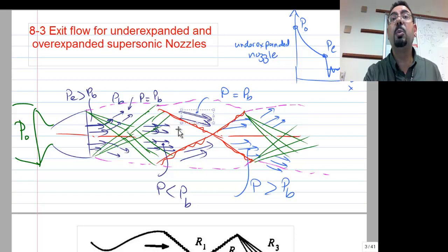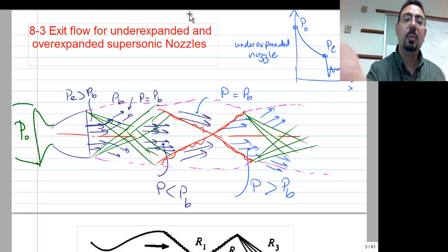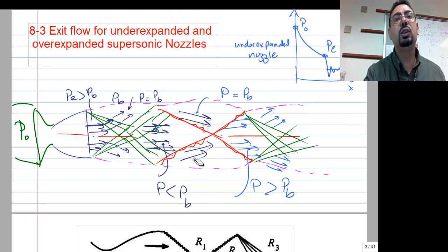So this goes back to back pressure, but of course as a result of those oblique shock waves, it starts going inward, right? So yes, you got the pressure right, but now you have the wrong direction, and so when you go inward, that shock wave will reflect as a shock wave, making your pressure higher but straightening you up. Now we have the right pressure. No, we have the wrong pressure. We have higher pressure but straight.